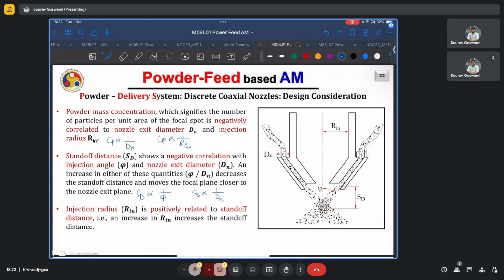Also, the deposition characteristics themselves have been optimized and tuned for a fixed standoff distance. Of course, with each layer the standoff distance varies, and that is why previously we also looked at some fundamental modeling of how the build height layers are changing with the change in the substrate geometry, to ensure that we are able to maintain a reasonably constant standoff distance, because it is important to maintain isotropic behavior.